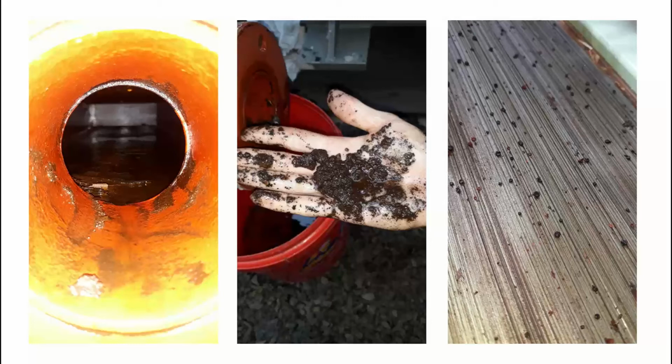Ampcontrol did a limited on-site internal inspection on this transformer after dropping the oil. The picture on the left is looking into a radiator via a bottom pipe. The orange is rust. We saw some paper in there from the windings, and you can see sludge at the base of the radiator. Likely this would be floating on top of the oil. We only inspected one radiator. The middle photo is sludge being pulled out of the radiator pipe. And the photo on the right is looking down on the top of the core, and we saw shiny metallic nodules, some of which had rusted. So very unusual.